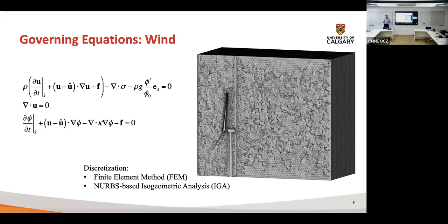So we're using a single Fortran code. Fortran F90, nothing can beat that, with MPI libraries, and we can easily turn it on, turn it off to make it applicable to one or another. So we're starting with the governing equation, which is the set of the incompressible Navier-Stokes equations.